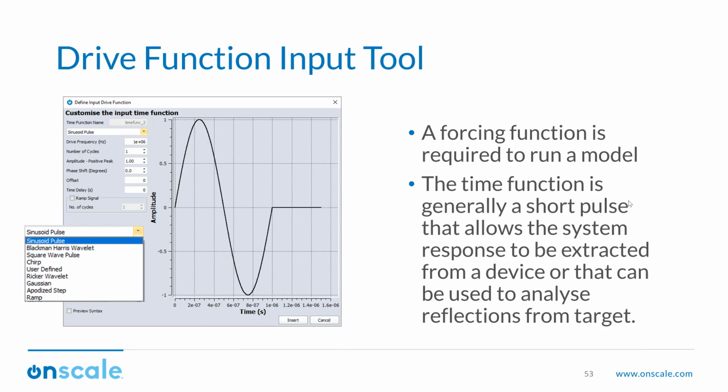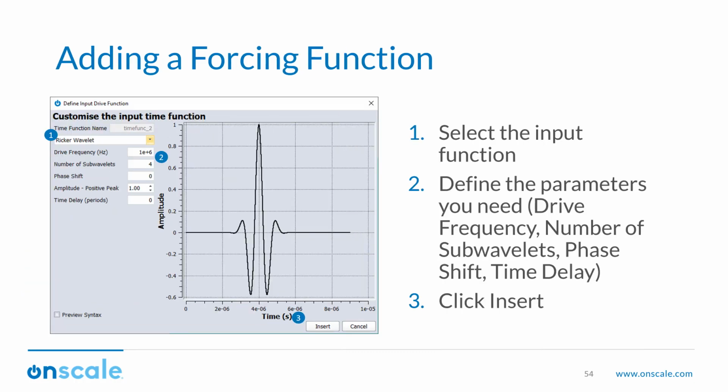What we look at is, okay, I send this pulse into the steel plate, and I'm looking at several areas of my plate. What is the actual time domain response from the plate, from the acoustic pressure inside the plate? From that, you can deduce a lot of characteristics about your system by looking at the output, knowing the input. Okay, now that we understand how it works, let's have a look at how to actually input that.